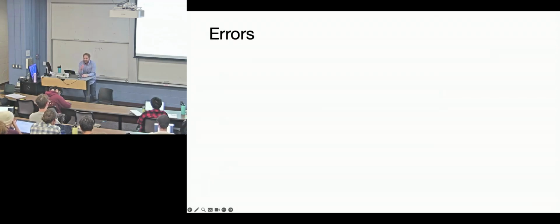So this is why you have to think about your entire system's ability to measure this analog value, and you may find that depending on your system settings, the second bit might be garbage, the third bit might be garbage, so you weren't that far off. Or you weren't that far off either. Your ADC is not some golden perfect Falstad simulation thing. It is impacted by noise significantly, and the first and second bits may just be garbage in your system.